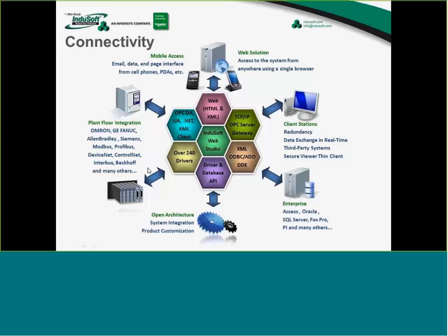Another key point that might be made here is because InduSoft has been around for so long, we still have a lot of the serial-based drivers that have been in the product for years and years. And for example, maybe you had a temperature controller that was only serial-based and you wanted to get that on a network or collect data to a database. Well, that in the past wasn't doable. Now with InduSoft Web Studio, you can get that information in via one of our serial-based drivers and send that to a database and get trend information or alarm information from those types of devices where that was never possible before.